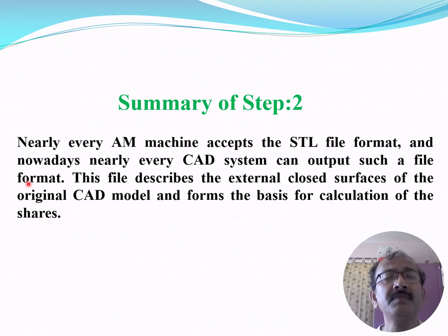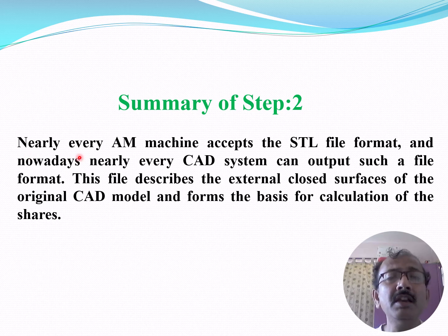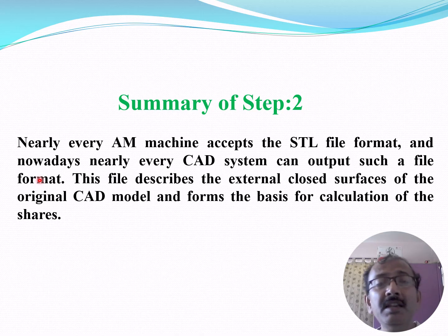Now the summary. Nearly every AM machine accepts the STL file format, and nowadays nearly every CAD system can output such a file format. This file describes the external closed surface of the original CAD model and forms the basis of the calculation of the slices.